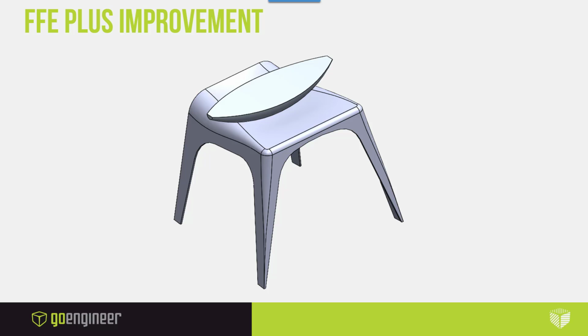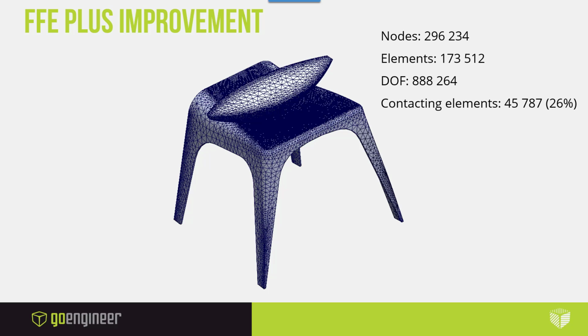To test the FFE Plus solver improvement, I ended up running this model. It's just a little chair with a pretty high density mesh. I ended up actually using the worst practices that we could think of, just to be able to make it very unstable. Overall, with the mesh controls on the faces that have no penetration contact, we ended up getting 170,000-ish elements, 888,000 degrees of freedom, and 45,000-ish contacting elements, which is about 26% of the entire study.